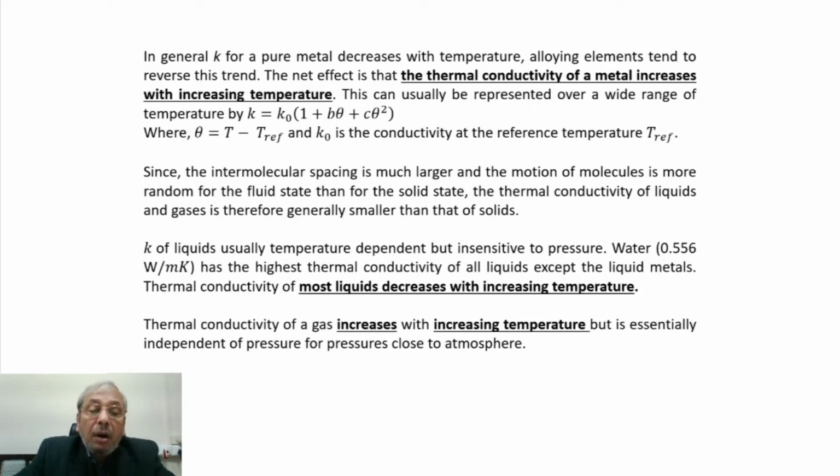Thermal conductivity of a gas increases with increasing temperature, but is essentially independent of pressure for pressures close to atmosphere. So for gases, what we usually encounter is that thermal conductivity increases with increasing temperature. And also to be mentioned that it is essentially independent of pressure for pressures close to atmosphere.